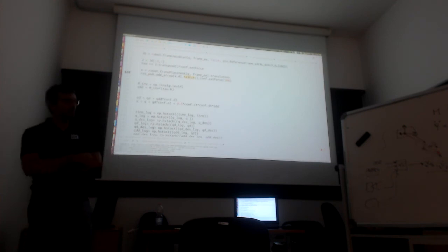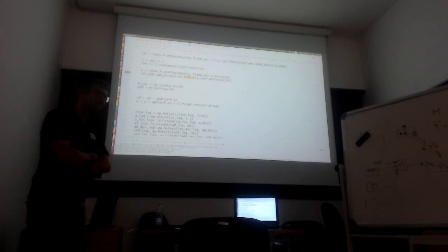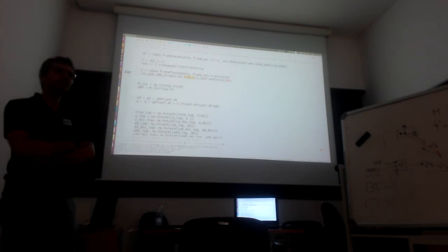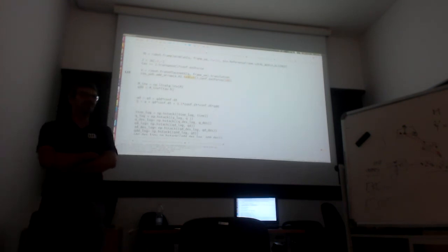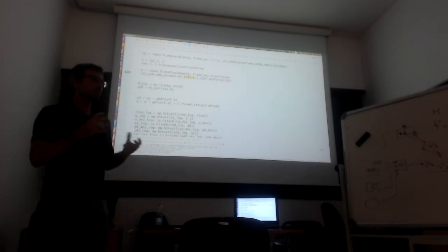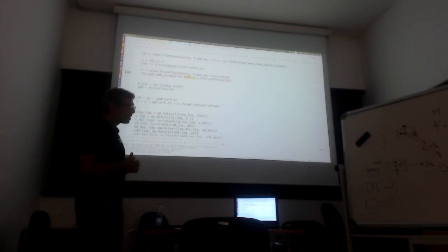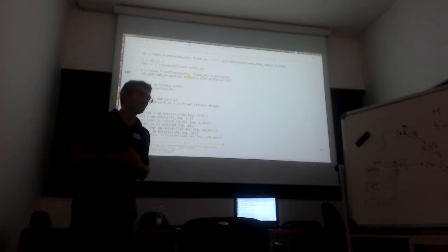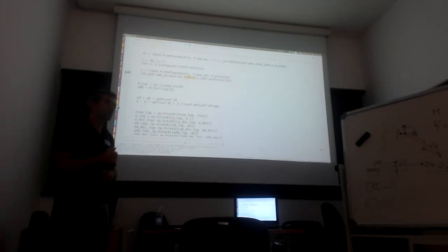And finally, what was the last one? Contact forces, no? Contact. Gearbox. The gearbox that allows us, in case of small electrical motors, to amplify the torque at the price of reducing the output velocity, and as a side effect, as the big drawback, to increase the inertia of the link, because the inertia of the rotor of the motor is reflected to the link side with the square of the gearbox ratio.